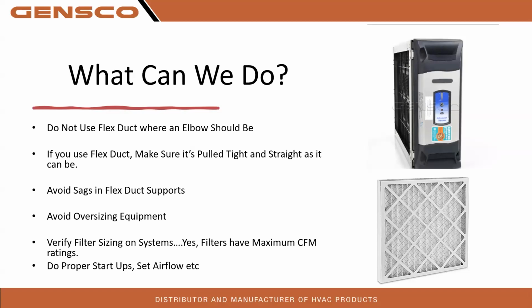Bigger is not better. Do not oversize equipment. Long run times. We got to have a proper run time to remove that latent load in the home, that humidity, right? If we don't do that and we're not actually exchanging the airflow, it's not going to work, right? CFM, cubic feet per minute. Anybody that's used to doing blower door testing knows we're talking about air changes an hour.